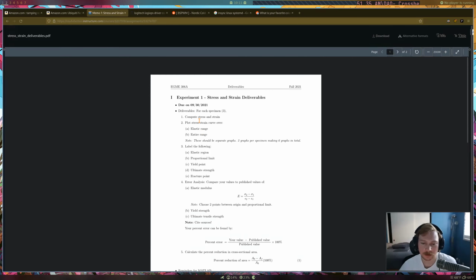Okay. So compute stress and strain, we just did that as a class. Plot stress and strain, we just did that. There are going to be two things you need to do. One of them is going to be for the entire range, which we just did. And another one is going to be for just the elastic range. So you're going to compress this down. You can go maybe up to the yield point. Basically, I just want a more zoomed in picture that's going to show the elastic range.